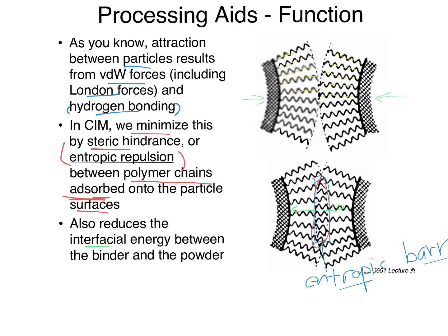It also reduces the interfacial energy between the binder and the powder, meaning that we can get wetting. Meaning that if we have a polyethylene chain, then we have the ability to have these polymers interact with a polyethylene melt around them. That's the other aspect of this. It's also very important. If it's sitting there in polyethylene, those chains will interface and solubilize in polyethylene. And that gets us to where we need to go as far as a homogeneous melt.